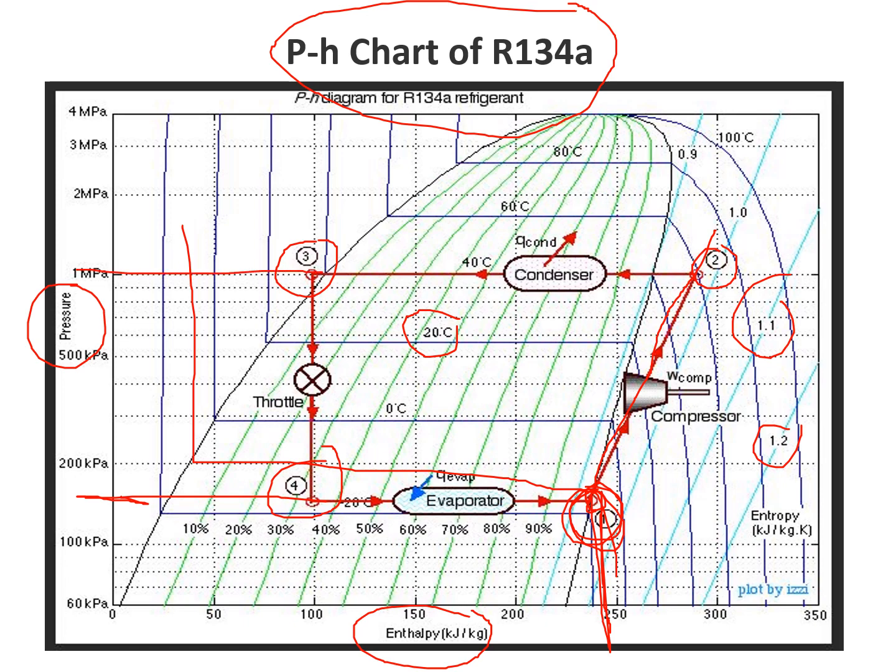Okay, so that pressure also you can measure by the device. So this is the pressure line of the condenser pressure, and this is the constant entropy line. Where these two lines cut, that will give you the state 2. Then you can measure the enthalpy at 2 with the help of that chart.